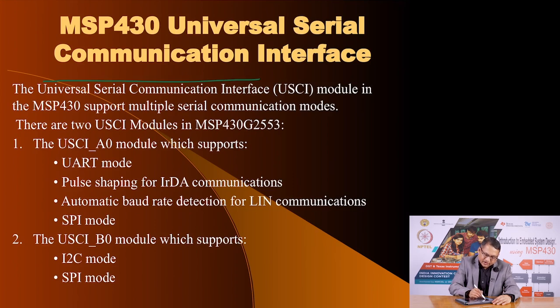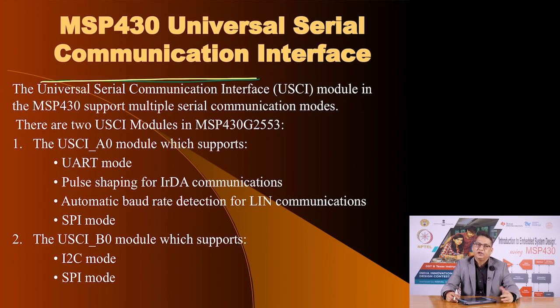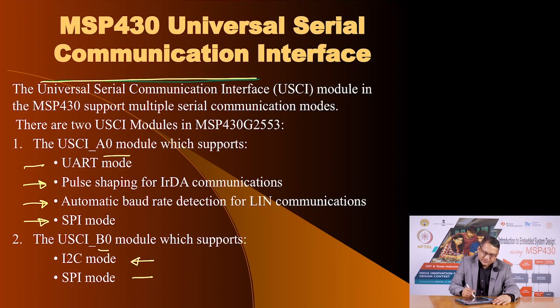The reason why they are called universal is because each of these modules offers support for multiple protocols. The A0 module offers UART, it has an infrared data communication as well as a LIN protocol and the SPI mode, whereas the B0 module offers only the I2C and SPI mode. So, if you want to have one UART and one I2C, it is possible. If you want to have 2 SPI, it is possible.